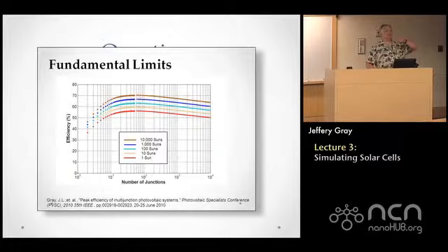And if you look at the efficiency curves, like just for 2 junctions, it's a very steep curve. Here you're exactly matched. If you change, let's say, the spectrum of the light just a little bit either way, you fall off of that. Whereas if they're electrically independent, it's a much flatter curve. So in fact, at the meeting that I came back from, there were 2 camps there. One that believed that we can pick the band gaps, it's not going to be sensitive enough that we worry about it. Another camp that really insisted that you really should have multiple terminals.